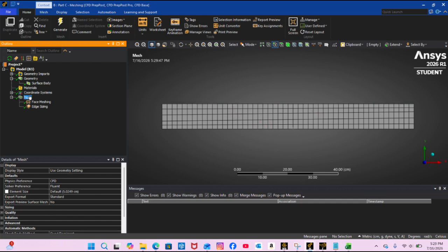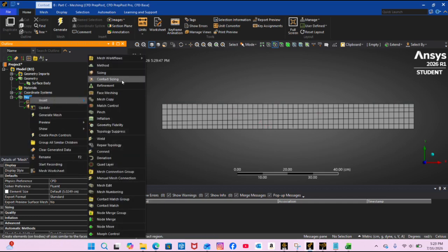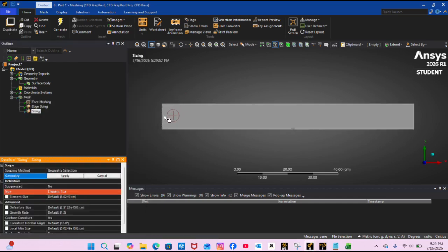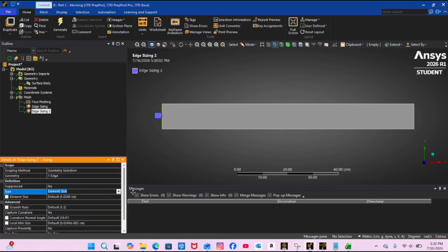So that's like this. And then again, we're going to do this 2 more times because we want to make sure that this is working perfectly, and each of these sides here is going to have different points. This one's going to be reversed from this one. So same thing, apply, element, number of divisions. This time we're doing 60 because we need these sides to be more detailed to make this mesh properly flow. So for this, you have to hit no.